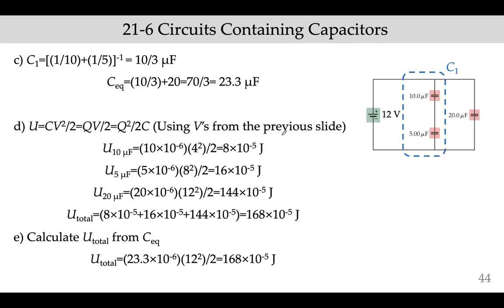Okay, so now we can also calculate the equivalent capacitance. First I have to start here because these two are in series. These two are neither in series nor in parallel, so I cannot really use this one first. What I have to do is find the equivalent capacitance first here. And because these are in series, I have to use the 1 over C formula here.